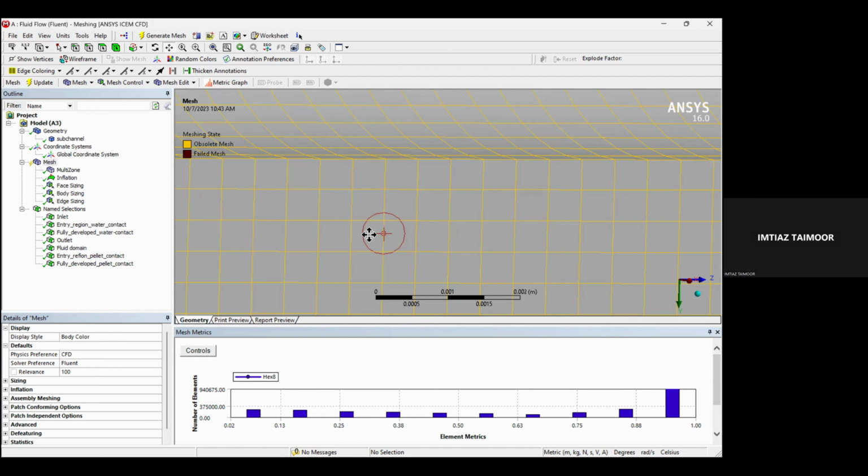So as I said, during the grid independence test, you have to increase the number of the nodes or the cells, and test whether my solution varies or not. Did I say that? Sir, varies and more accurate.